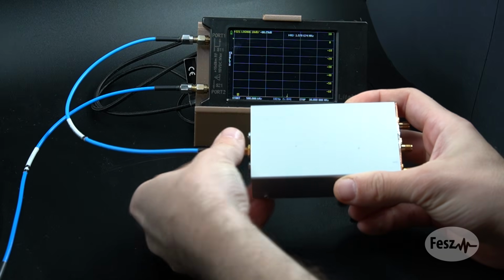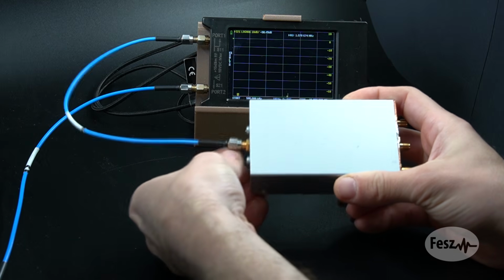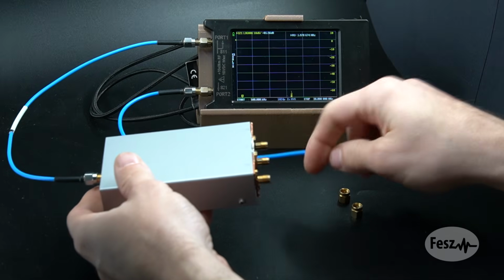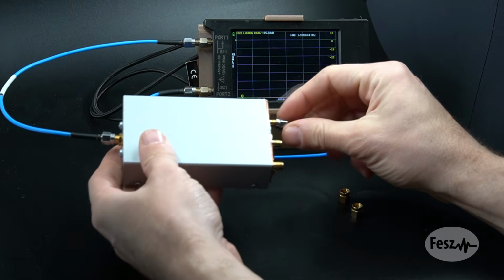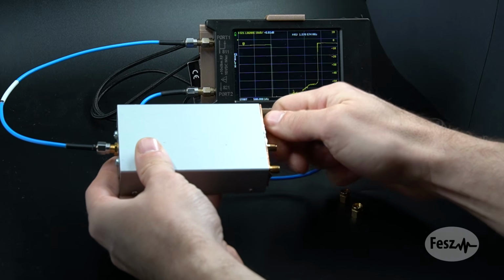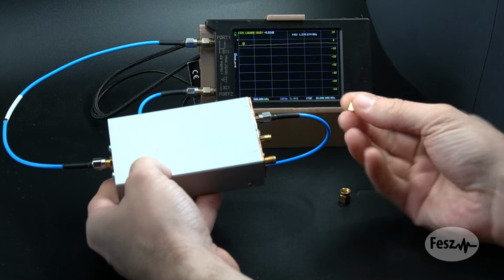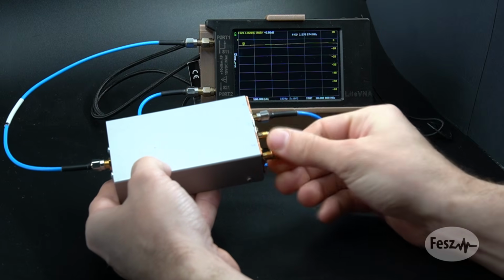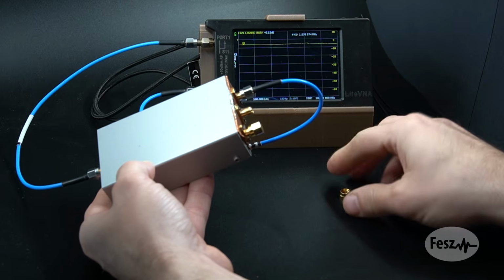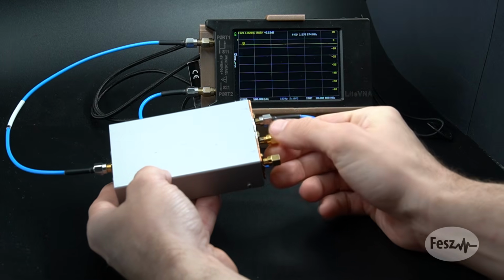To test it out, there are 2 main tests I wanted to perform. So first off, check the insertion loss: how much signal passes through each port. In an ideal world, the target would be 4.77 decibels, but I'm pretty sure it's going to be a bit worse. Anyway, I set up the VNA to insert signal on the input port and measured all 3 of the output ports, one at a time.